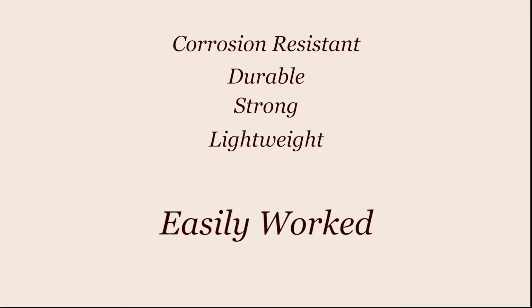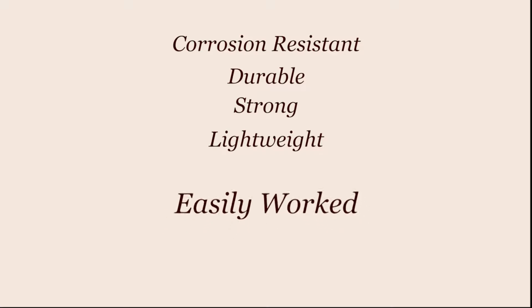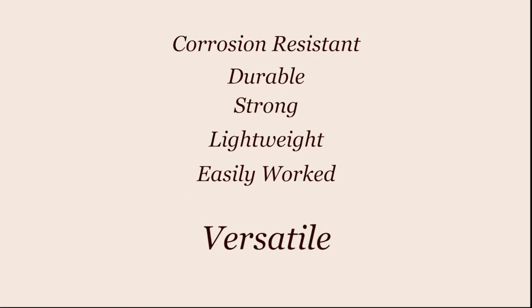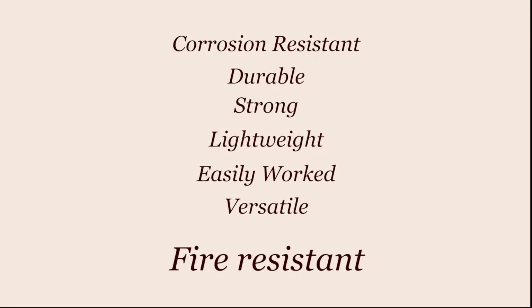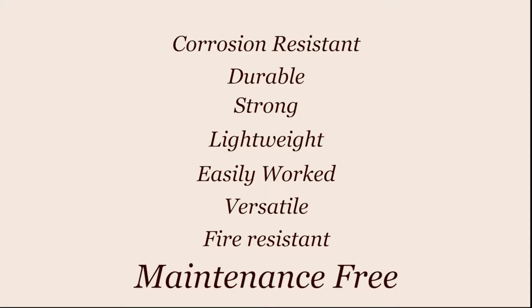PFRP shapes can be field fabricated by carpenter trades with standard tools and easily lifted into place during installation. Molded FRP can be fabricated into complex shapes. FRP can be made fire resistant with certain resins and additives. FRP does not require painting or other treatment.